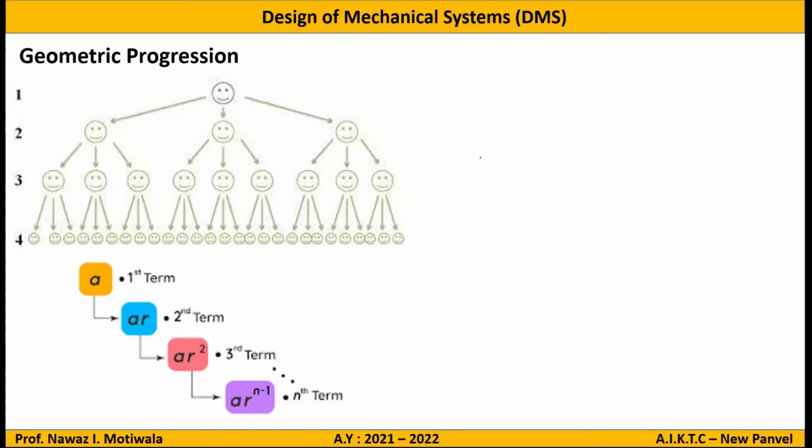So on the same lines, let us say if I give you an example that my n1 is 100 rpm and I am giving you the common ratio phi is equal to 2. That is common ratio. So can you tell me what is n2? What can be n2? 200. 200. What you do is n1 multiplied by phi, correct? Phi means that Greek letter phi. Yes. Okay. So will you get the answer? n1 into phi करोगे तो आंसर आ जाएगा for n2.